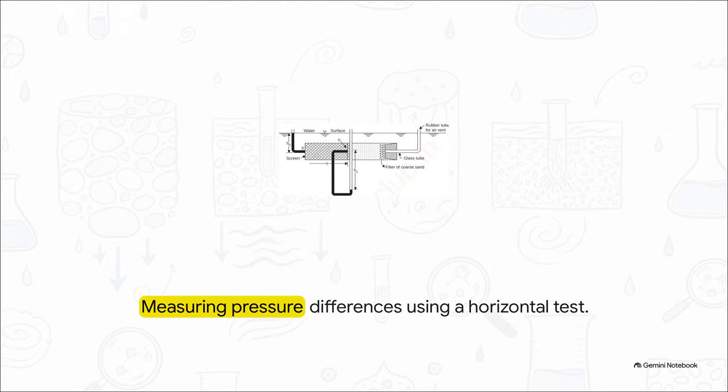Moving on to the squeeze, capillary pressure. Now, this gravity-defying stunt definitely doesn't come for free. Holding millions of microscopic water columns in the air creates a massive physical reaction inside the soil itself. To figure out how intense this pressure gets, engineers actually measure it using a horizontal capillarity test setup. By forcing water horizontally through a soil sample inside a glass tube, they can isolate the forces at play.